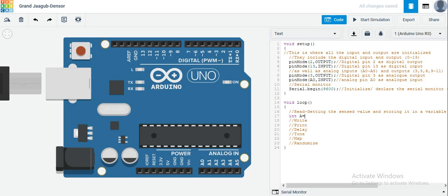So you can also do digital or analog read. In this case, I can start with digitalRead, and please remember our digital input was 13. Which means you will connect a device to 13, which will be giving you the sensed digital value. An example of such is the button switch, which you are going to use. So you digitalRead from 13, because that's what you declared here as the input, and then close.